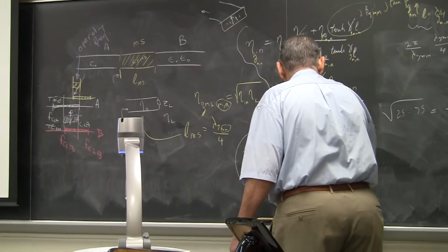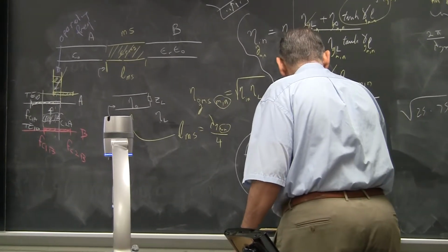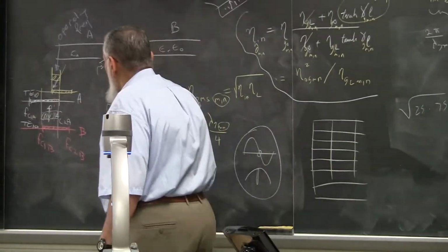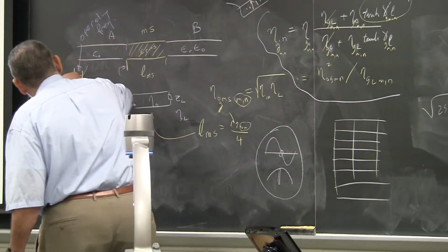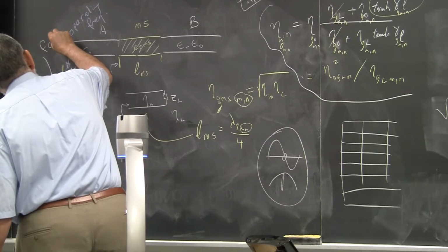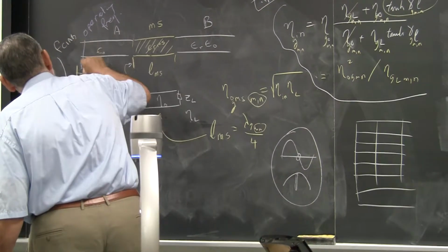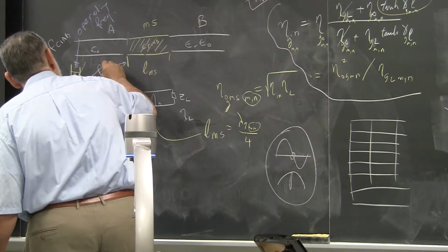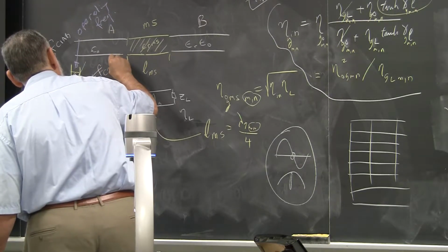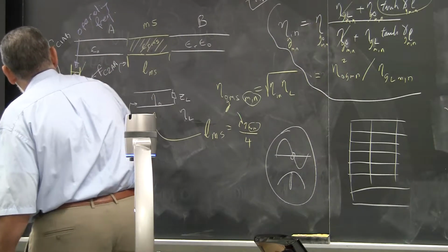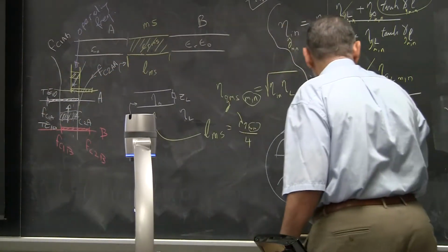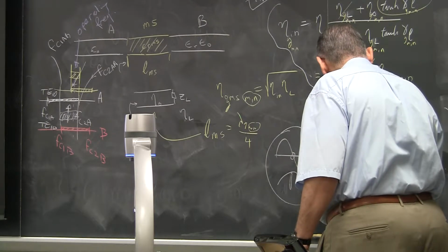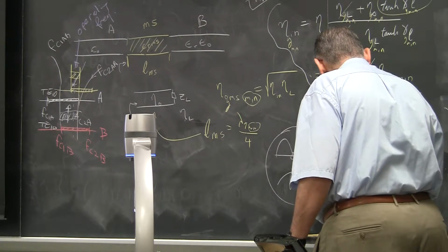So make a tabulation, write your code, so you can produce from, we'll call this one here FC1AB and FC2AB, which is the cutoff frequency of the common A and B. So you start with FC1AB, and you increment here all the way to FC2AB.